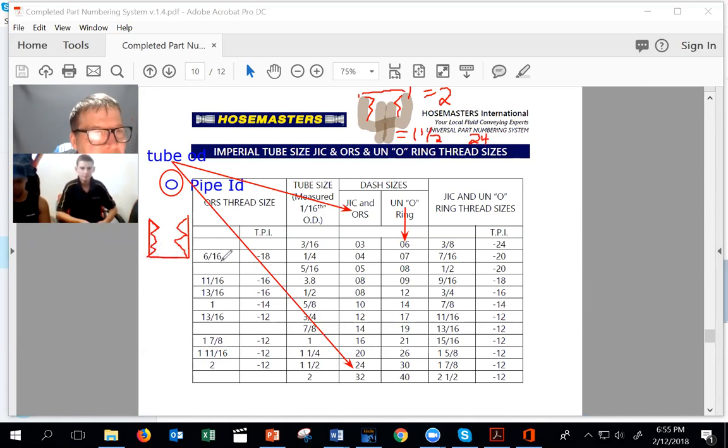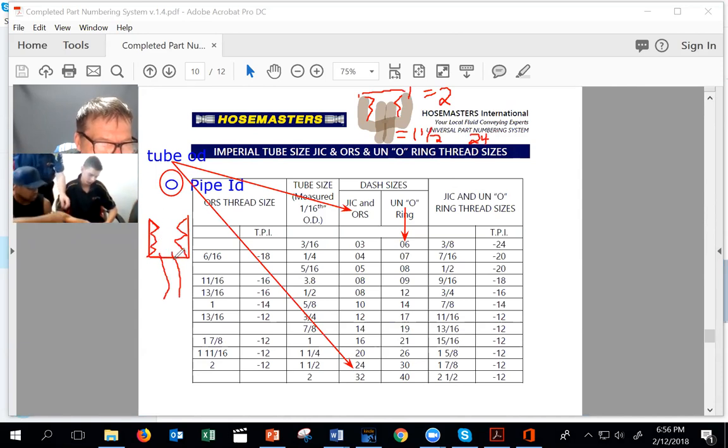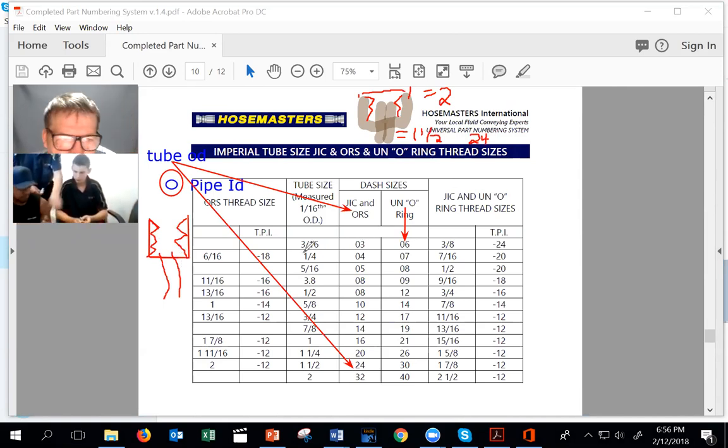That's where it seals. You have the tube coming down through here, but it seals right there. It anchors here and it seals there. Look at that. You can see how that sits hard against that, and the thread pulls it together, and then the O-ring will seal it. So it'll lock itself.